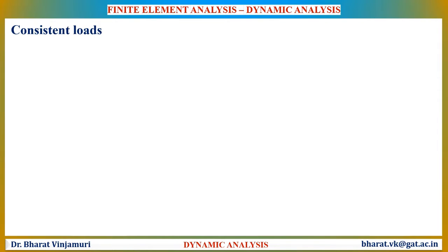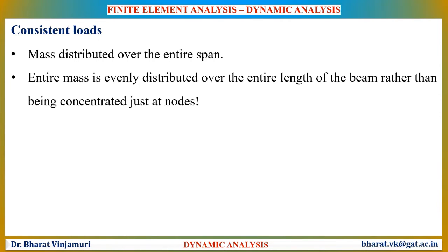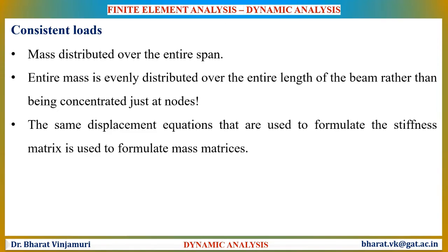In case of consistent loads, it is understood that the mass is distributed over the entire span. That is, the entire mass is evenly distributed over the entire length of the beam rather than just being concentrated at the nodes. In this case, the same displacement equations which are used to formulate the stiffness matrix of the structure can be used to formulate the consistent mass matrix.